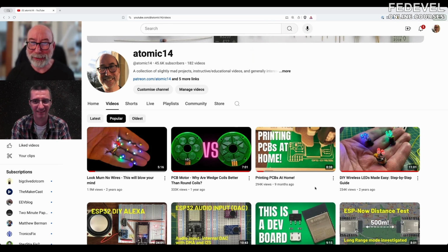Yes, it's like 3D printing back in the early days of 3D printing. You have to experiment, and sometimes it doesn't work exactly as you expect. Yeah, and sometimes the nozzle gets clogged and it doesn't print any ink, and then you have to replace the nozzle because it's blocked and there's no way to unblock it, and the ink's very expensive. So now it's not really necessary unless you really need a PCB prototyped right now. Then it's just a bit of fun, I think.